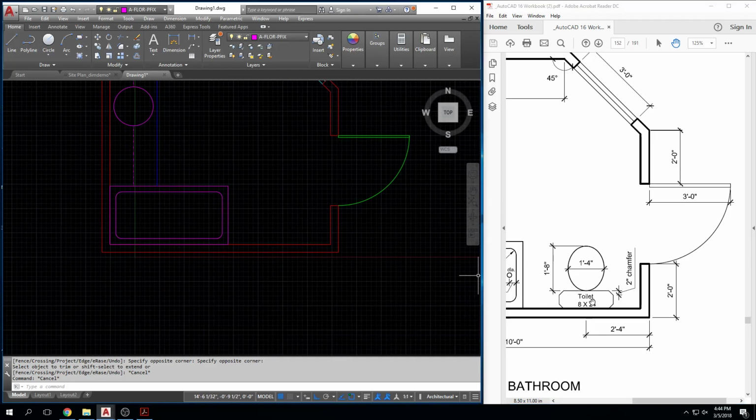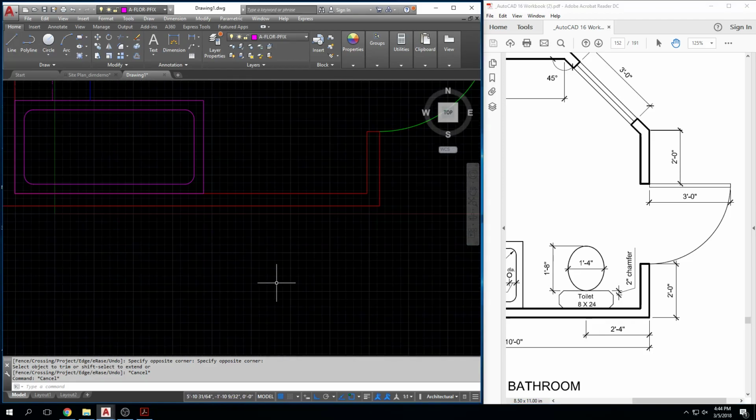So let me draw this 8-inch by 24-inch rectangle. I'm going to click on rectangle, click, I'm going to type at 24,8, enter. Right, that's a relative input, and it was at 24,8 because I went over 24 inches and then up 8 to create that.